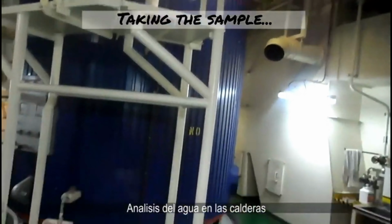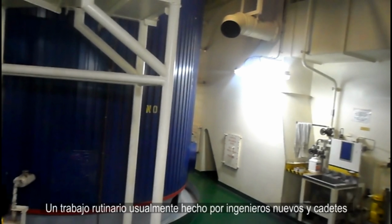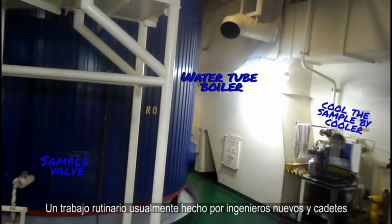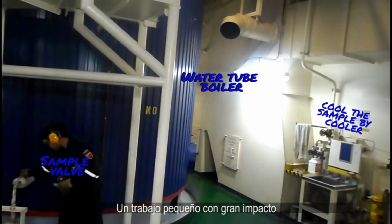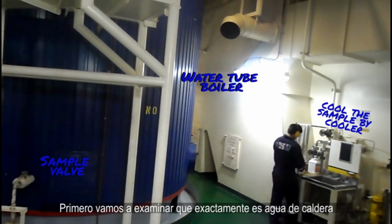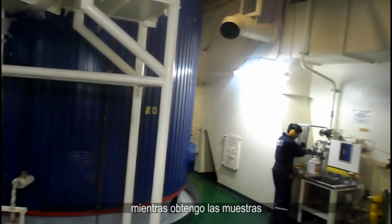They take a water sample at high temperature from the boiler, which is at high pressure, and they have to manually check whether the water sample is at an optimal level. First they bring the sample to room temperature and then measure its pH value and conductivity value. If the pH value is acidic, they have to calculate the volume of base chemical that should be added to the boiler water. And if the conductivity is not at an appropriate value, they also have to calculate the volume of water that should be removed from the boiler.